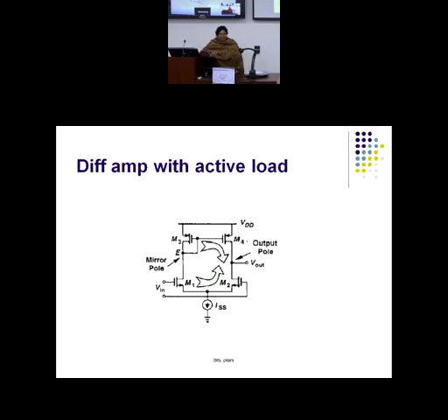So we do not directly allow the pad to connect to the differential pair, because input pad capacitance is very large. So there is an isolation between the two nodes; you do not directly connect the two together. That is the reason that the pole omega in is normally not shown in the textbooks. By default they assume that this is at a high frequency, does not affect your gain bandwidth, UGB range, and does not come within that range. In many books you will not find this pole computed.